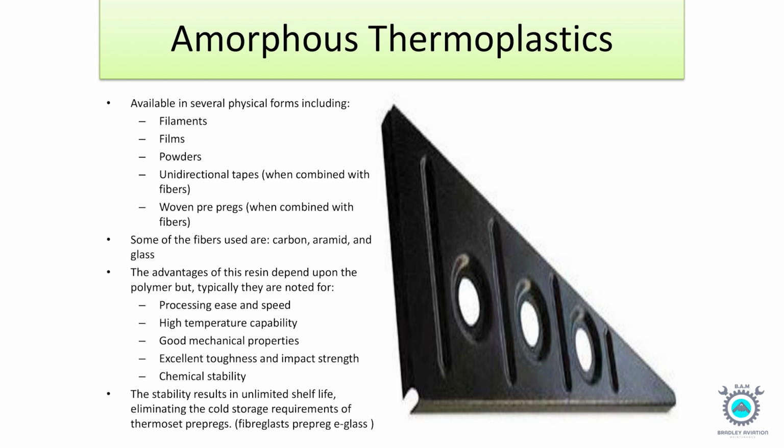The advantages of this resin depend upon the polymer, but typically they are noted for processing ease and speed, high temperature capability, good mechanical properties, excellent toughness and impact strength, and chemical stability. The stability results in unlimited shelf life, eliminating the cold storage requirements of thermoset prepregs.